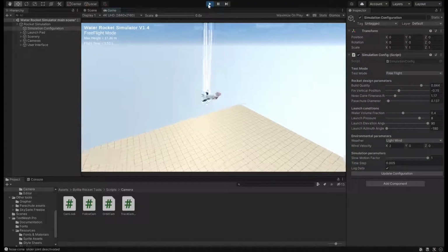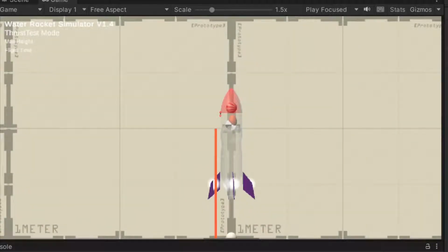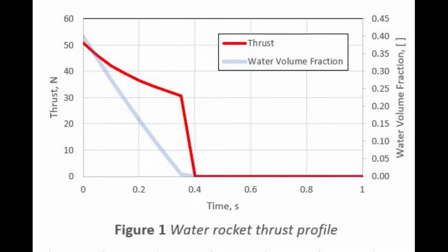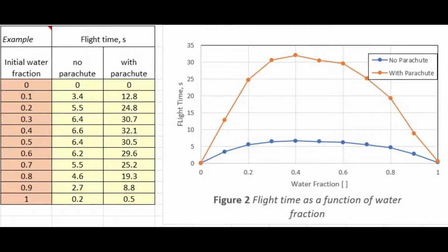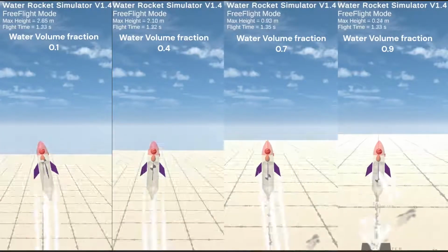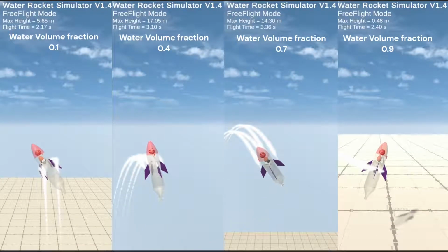Propulsion. The propulsion system of the rocket has three parts: air, water, and pressure. When the rocket's water fraction is altered, the impulse varies. The rocket is filled with 40% water. Then air is pumped into the bottle, which pressurizes the rocket and causes the rocket to launch. The elastic potential energy of the air forces the water out of the nozzle, which provides the thrust. Impulse is the change in momentum. The momentum before launch is zero, therefore after the launch, the momentum needs to be conserved. So when the water is forced out of the nozzle, the rocket must fly in the opposite direction.